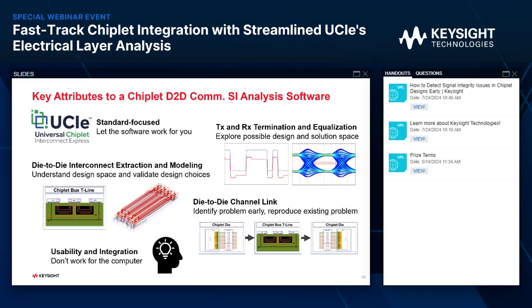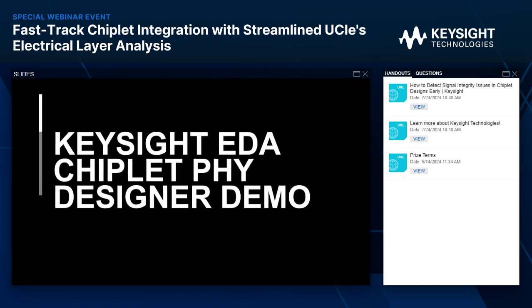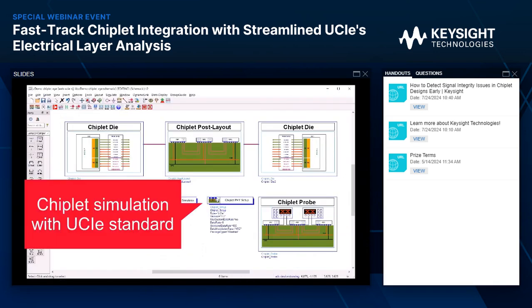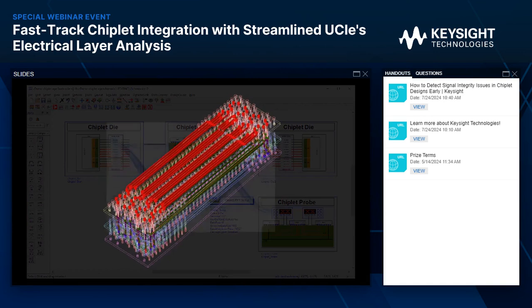Now here's a demo of the chiplet PHY Designer from Keysight EDA that really matches all those key attributes. Welcome to the Keysight EDA Chiplet PHY Designer demo. In this demo, I will show you how to set up a chiplet simulation with a die-to-die interconnect EM model as the channel. We will look at the resulting eye and compare it to the UCIe eye mask.